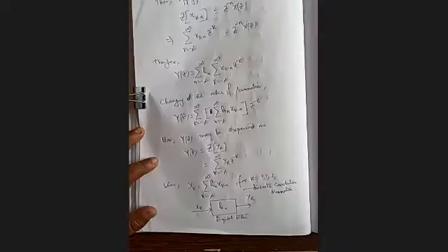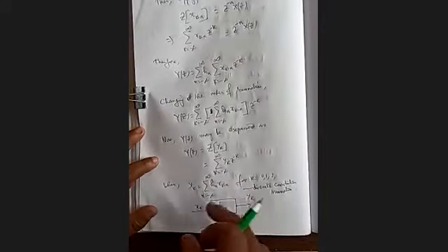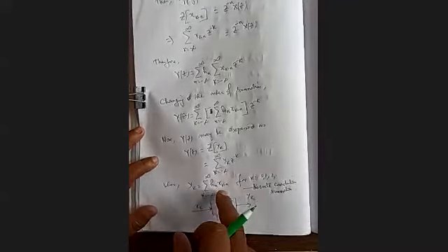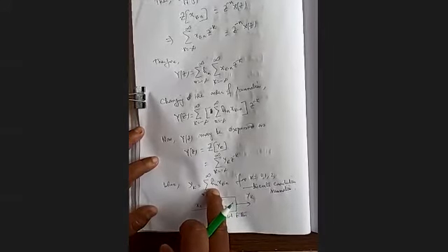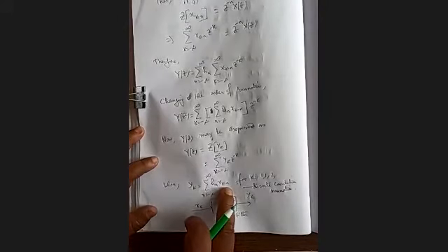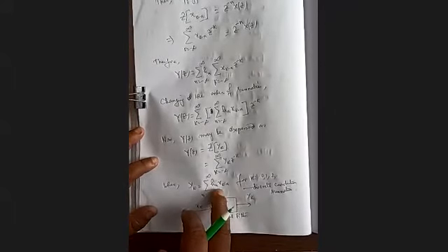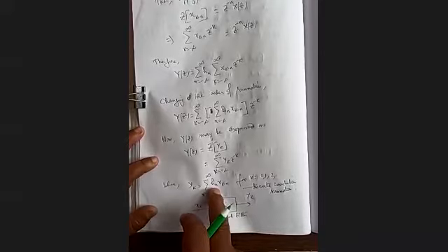In the previous class, we concluded with the concept of convolution sum, where the impulse sequence coefficients Hn are multiplied with a series of inputs and its delayed versions, Xk minus n. These various delayed inputs are multiplied with the filter coefficients, or impulse response of the filter, to give us the output.